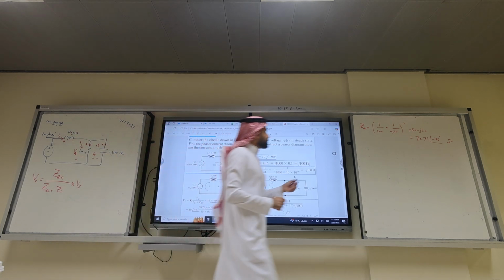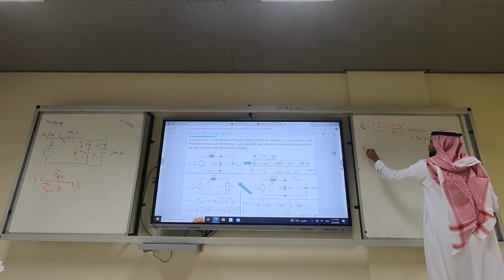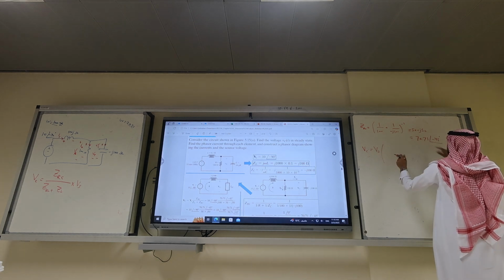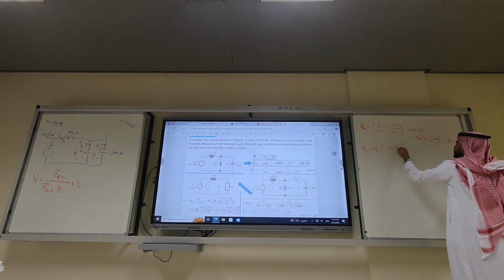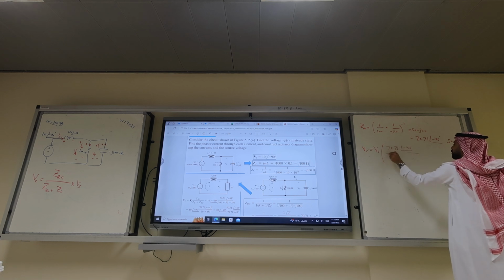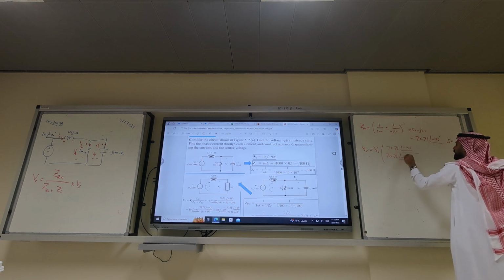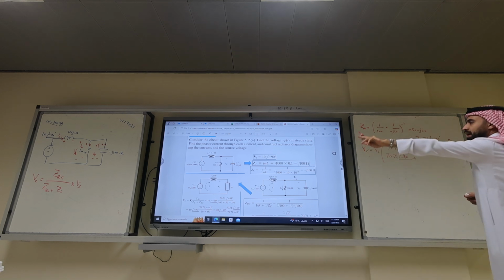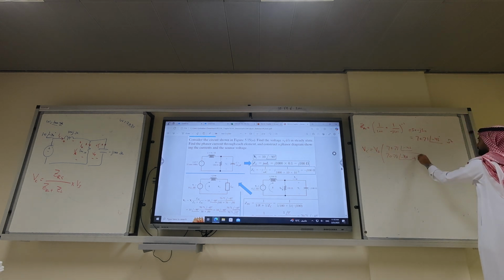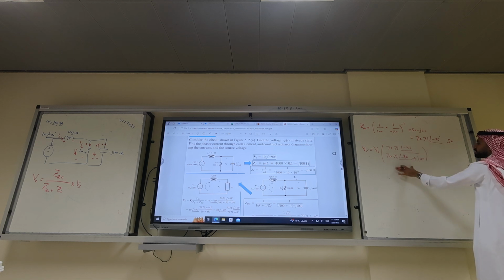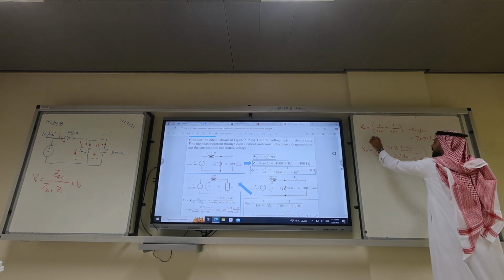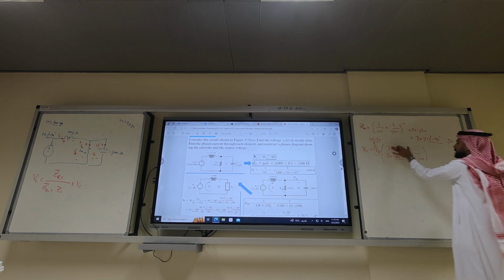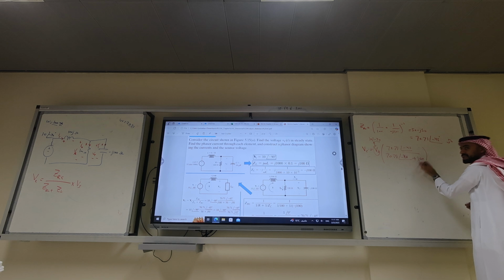So let's do it. So VC equals VS times 70.71 angle minus 45 over 70.71 angle minus 45 plus J. What is Z sub L? 100J, right? And we know VS. Can you remind me? It's 10 angle minus 90. So this number times this number over this number plus that number, do it.